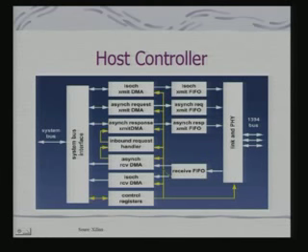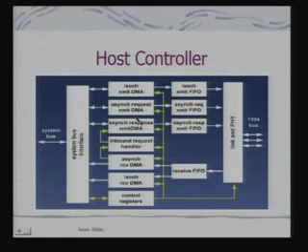Now, these FIFOs will obviously be connected to what? If you are looking at a host interface, they will all be connected to the various DMA channels, because this data has to be transferred to the memory area, so that the processor sitting inside the embedded system can make use of this data. We have not looked at this interface for other buses.